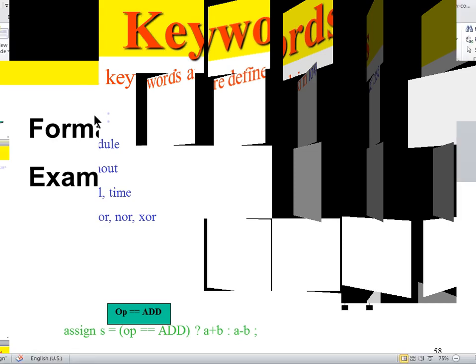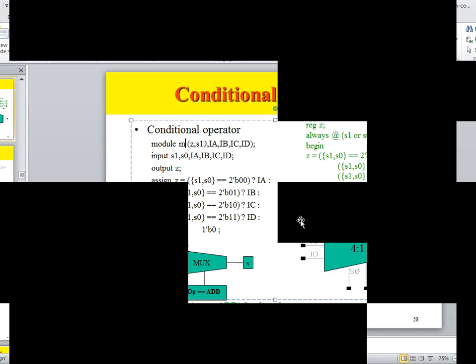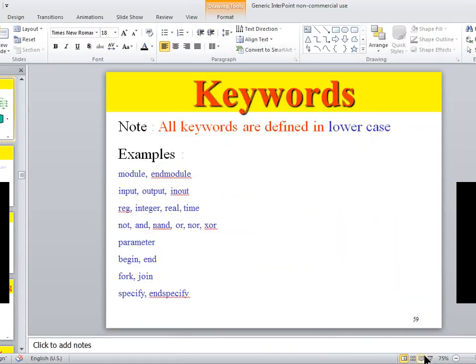In this case, the name of my module is mux41, because it's a 4:1 mux. I could technically call it MODULE in capitals and it would be accepted, because only lowercase module is a keyword. But calling a module "module" doesn't make sense, so I will call it something relevant to my design. All the keywords have to be lowercase. Anything that you use in lowercase has to be in lowercase throughout the design. Any signal names in uppercase have to be in uppercase throughout the design.